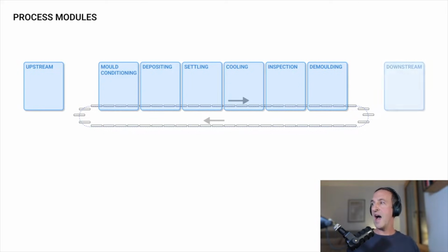And then afterwards, after your application, after the molding line, you would have the downstream module. And a downstream module can be, for example, a buffer between a molding line and a packaging line, something that temporarily stores products and prevents bottlenecks and improves the workflow.